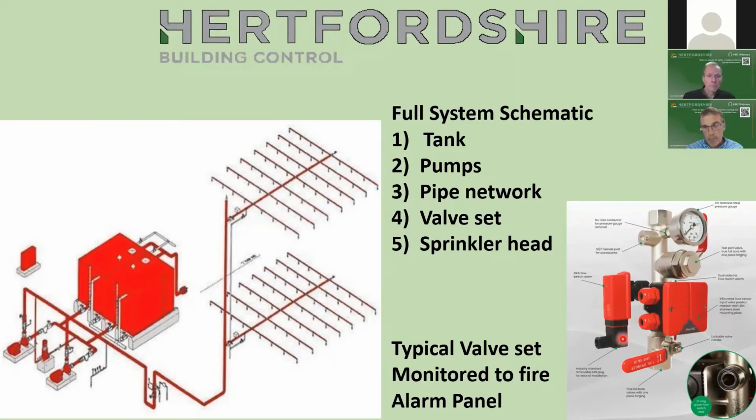All of these valves now are all monitored, and they'll be interfaced back to the fire panel. So if any of these are accidentally left open, there'll be another isolation valve there, there'll be a flow valve there, and sometimes there's an isolation valve in every unit. And there really should be, and it's touch and go whether those isolation valves need to be controlled. It's not controlled in the code, as far as I'm aware, but it'd be ridiculous not to have them controlled. Either that, or you'd lock them open, find somewhere of doing that.